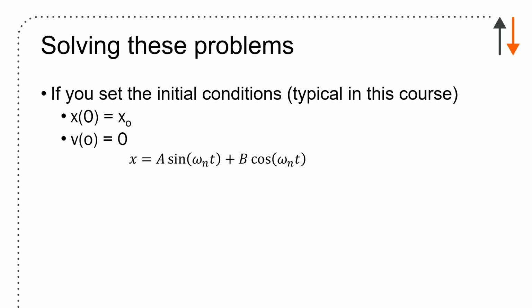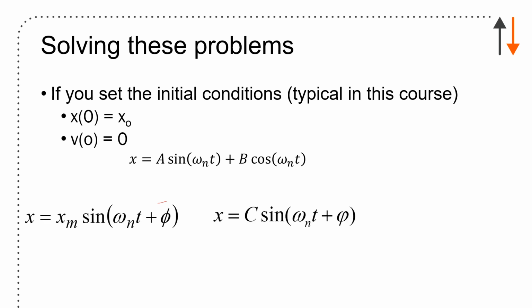If you say v is equal to x dot, then you get v naught is equal to, because this cosine term remains, this sine term goes away, a is equal to v naught divided by omega n. And often you find that these are relatively simple equations to solve, to set up. And really, we often ask you just to set them up, not much more than that. But it's really doing the force balance that's challenging.